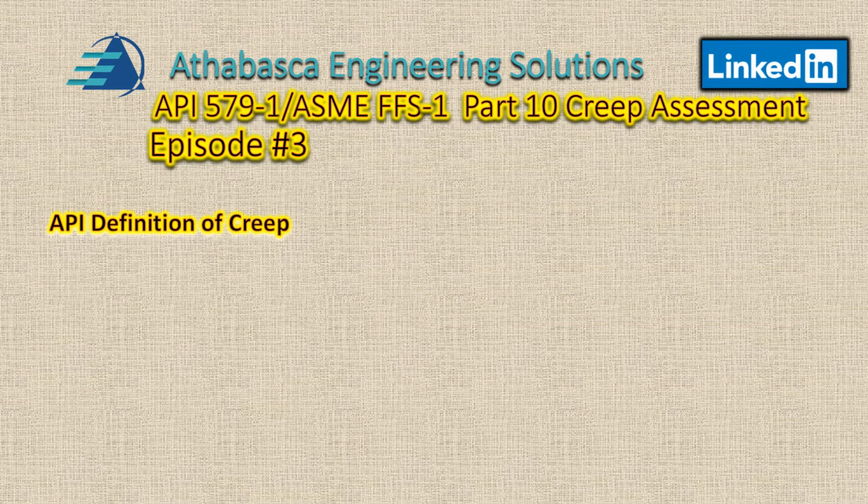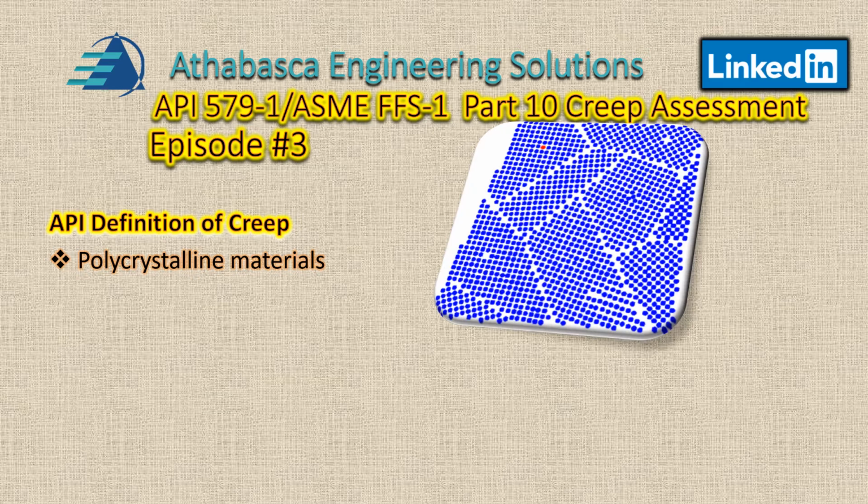API has a very specific definition for creep. Creep is, of course, a very broad topic, and it has to do with dislocation motion, but let's start off right now with some basics. All materials that API uses are polycrystalline materials. That means it has a lot of different grain boundaries of different shapes. And inside each of these grains, the structure is uniform, but there are flaws.